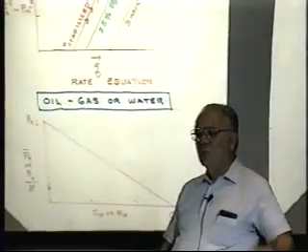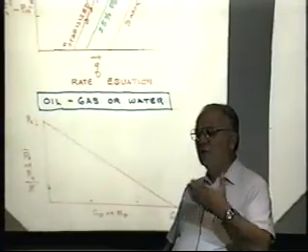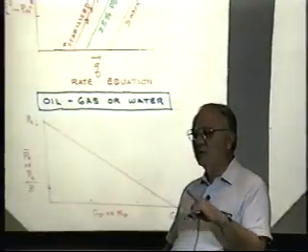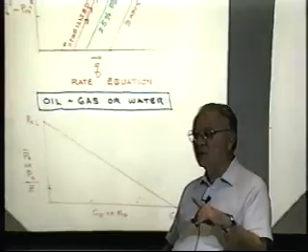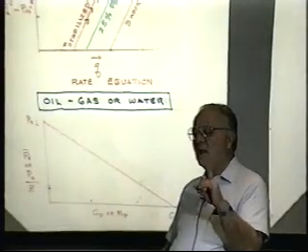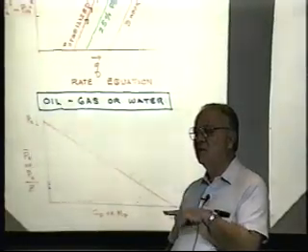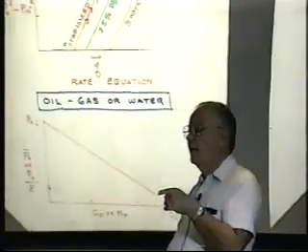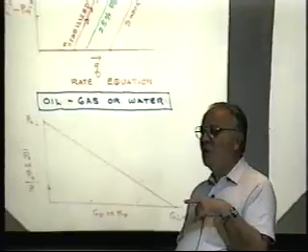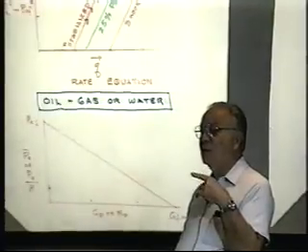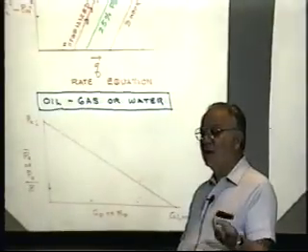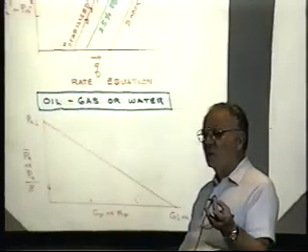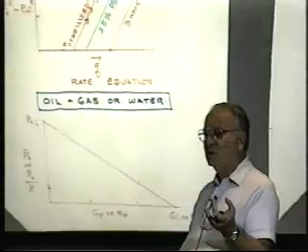So through the use of these very simple equations, we were able to figure out it was a layered no crossflow reservoir. And we modified program 7151 to do layered no crossflow forecasting with that program. And then we used the model, and guess what? We got the same answers with the hand calculation, the 7151, or the 3D model with layered no crossflow.